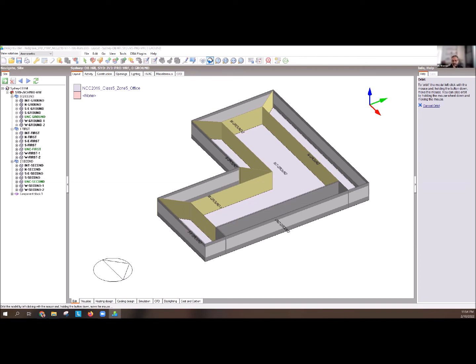What are those three values I showed you? U value, solar heat gain coefficient, visible daylight transmission. Those are the things you need to understand. And then U values, R values, all of that, you can start from the ECBC requirements and then improve on them or change them. And then shading might help, those kinds of things that Mansi was talking about. All those things would help to improve your design. I hope that answers the question.